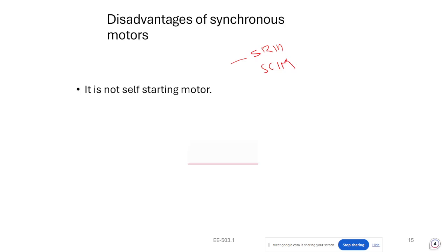Let's talk about our ceiling fan. If we turn on the switch, it starts. But in that we have a mechanism that produces a rotating magnetic field, due to the two phase machine. That is, a single phase to two phase conversion takes place. That's why it self starts. If we remove the capacitor from the ceiling fan, that ceiling fan doesn't run. Similarly here, that is why it's not self-starting.